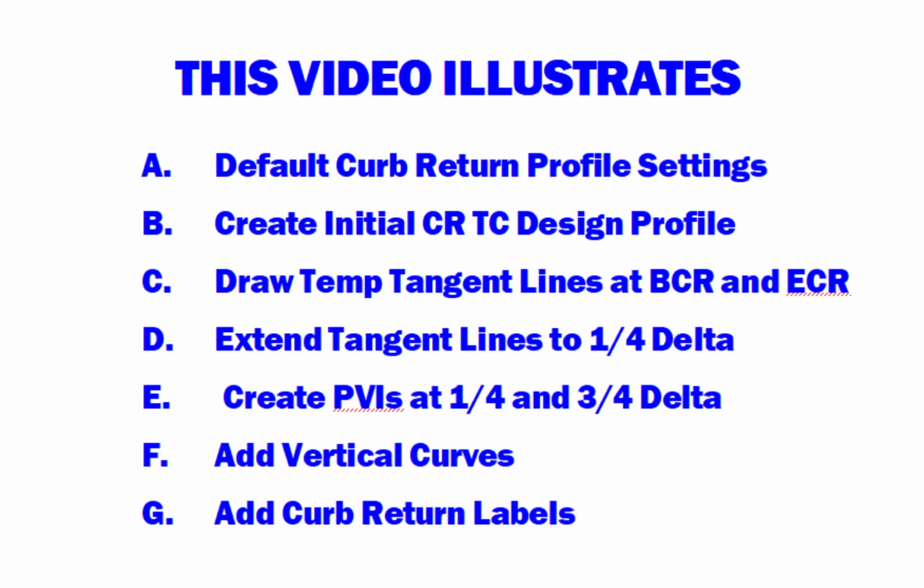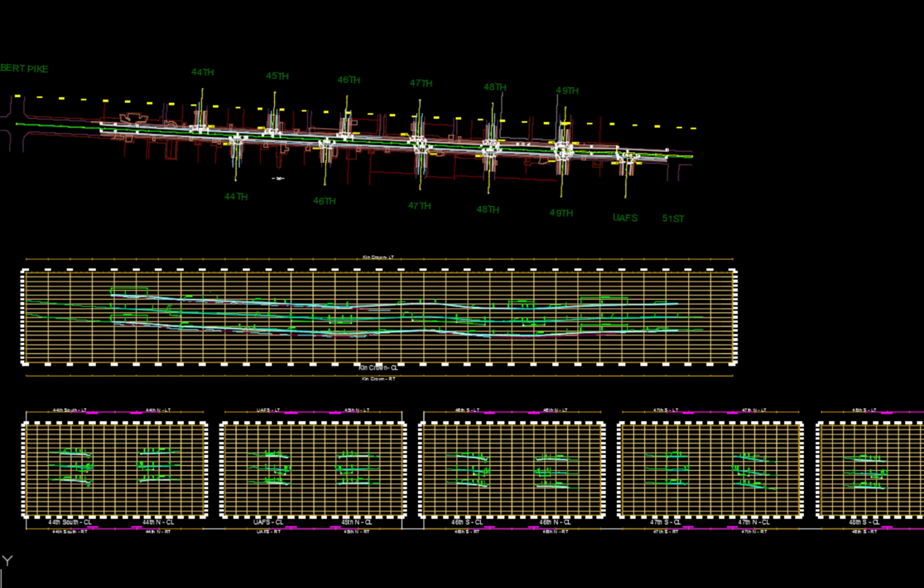G. Add curb return labels. The curb return profile is an extension of the side road top of curb profile from the BCR-ECR on the side road to the ECR-BCR on the primary road. The profile consists of double reversing or compound vertical curves with the PVIs at the 1/4 and 3/4 delta points